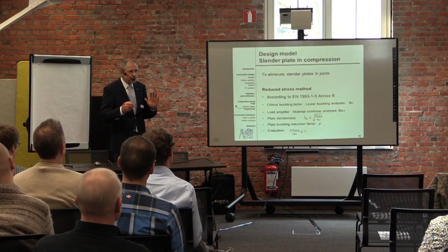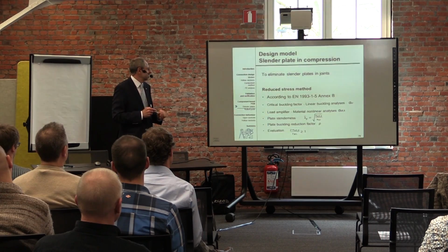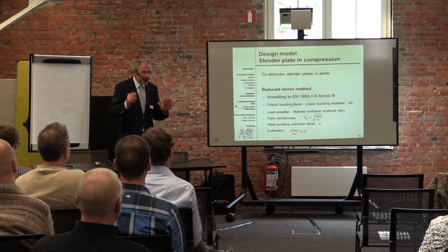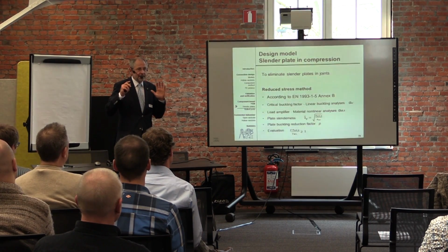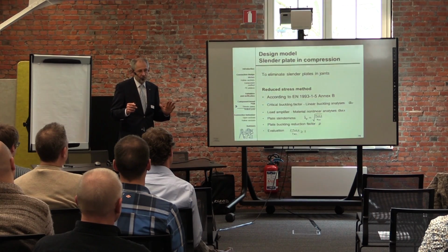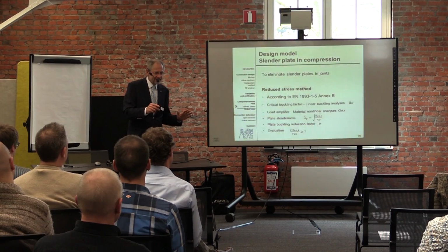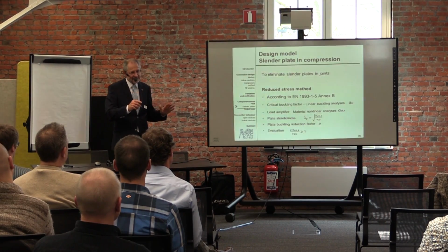we took fully Annex B from Eurocode 5, and maybe you are aware, maybe you are using it every day, but I would summarize. It is the procedure how to check the resistance of a plate in buckling for complex shape webs.